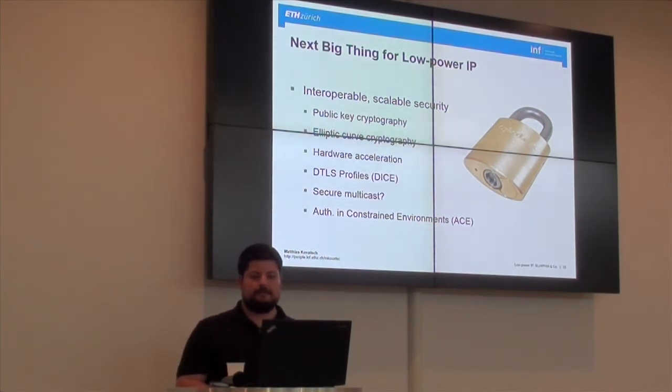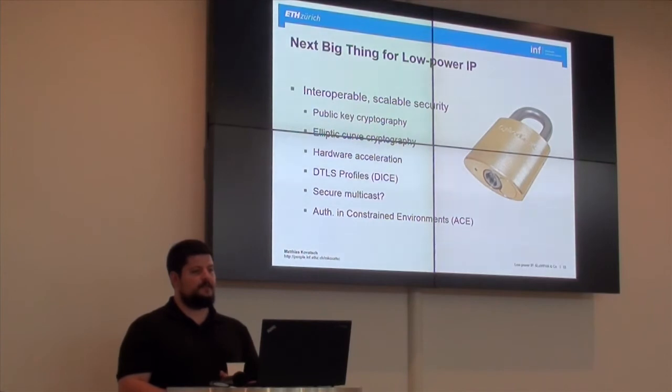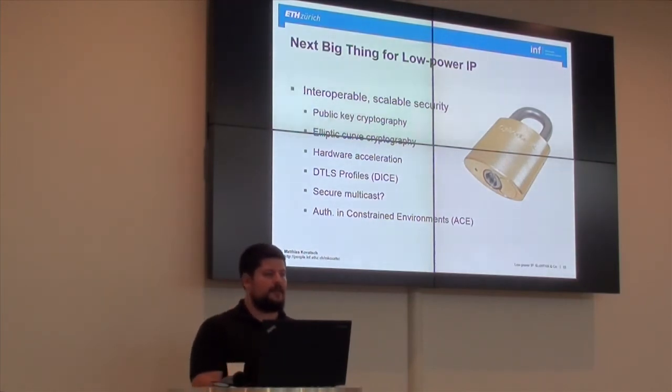So a good playground for 6LoWPAN is definitely Contiki. I prefer it over TinyOS because it's just C, so it's really easy to port it to a different platform and just connect something to an I/O port. It's much harder, in my opinion, with TinyOS, where you have an abstraction layer in between, do some VHDL-like wiring, compile it together and then get the binary out of it. So the plain C model is something nice if you really want to play and solder and so on. And Contiki has good coverage of this whole low-power IP stuff. It's sometimes not fully RFC compliant, but there are quite some efforts to improve on that. And it's open source, and for that really great.